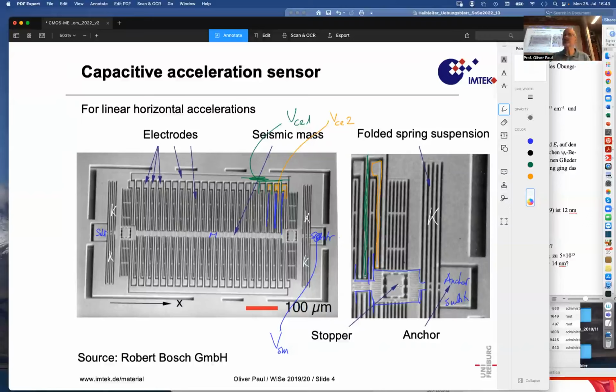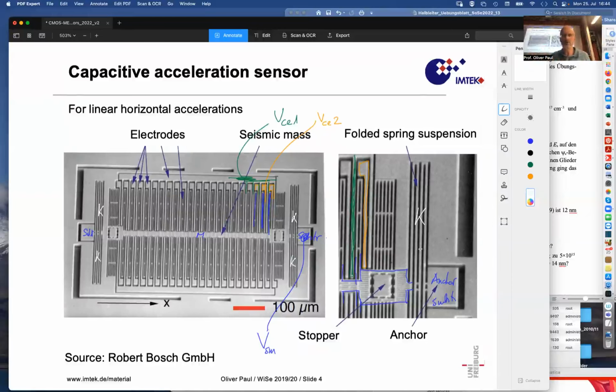It's an art to design these stoppers. So this is not the newest version, because objects bumping into each other cause fracture, debris, blockage, everything. So usually after a really hard event has happened, you replace the accelerometer. You put in another one because you don't know what happened. But anyway, there are many ideas to design stoppers that move less violently into each other, more smoothly, that make sure this stopping does not cause excessive overloads of the material.